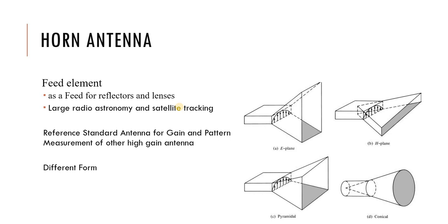As you know, the horn is nothing more than a hollow pipe of a different cross section, which tapers onto a large opening and aperture. The type, direction, and the amount of the taper or flare can produce many shapes, and it extremely affects the overall performance of the element and the antenna as a radiator.